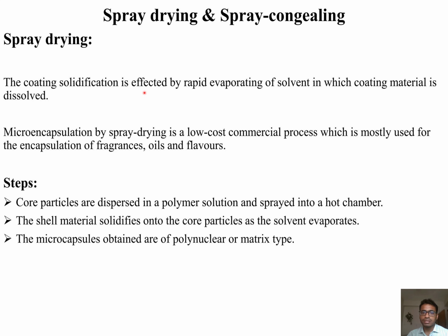So the coating solidification is affected by rapid evaporation of the solvent in which the coating material is dissolved. Microencapsulation by spray drying is a low-cost commercial process, mostly used for the encapsulation of fragrances, oils, and flavors. Steps: core particles are dispersed in a polymer solution and sprayed into the hot chamber. The shell material solidifies onto the core particles as the solvent evaporates. The microcapsules obtained are of polynuclear or matrix type. Usually spray drying is nothing but the spray drying of tablet coating. This process is similar to the previous one.